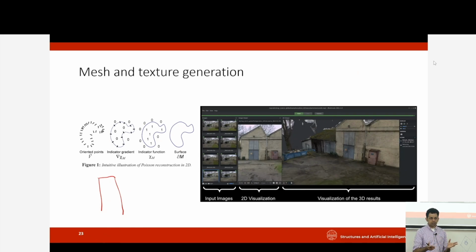So there are some assisted ways to do it, but you don't necessarily need the mesh. Even from the point cloud, people have been proposing deep learning methods where you can extract coordinates of the section, and then you can extract the elemental connections.